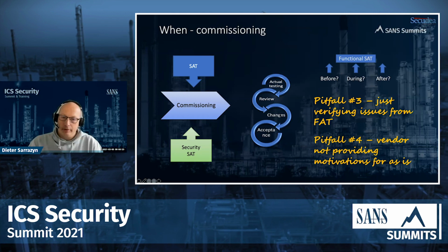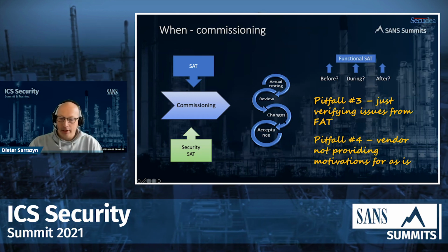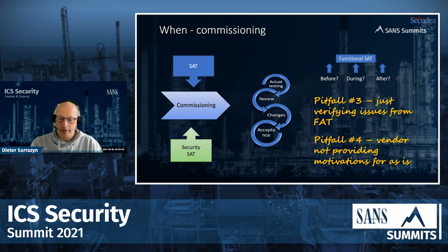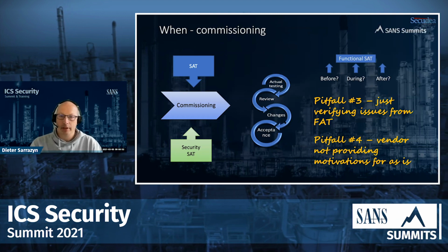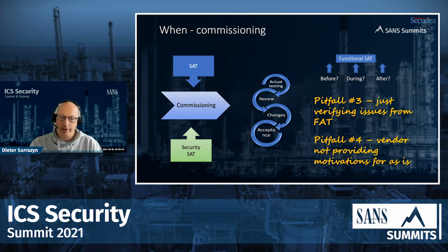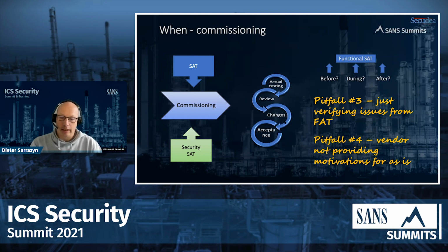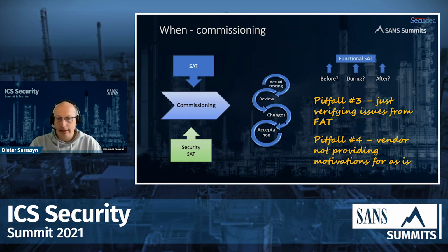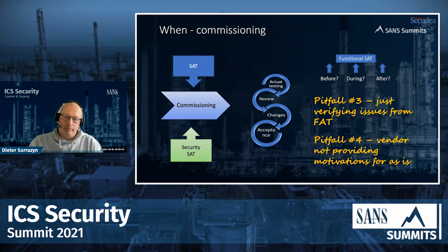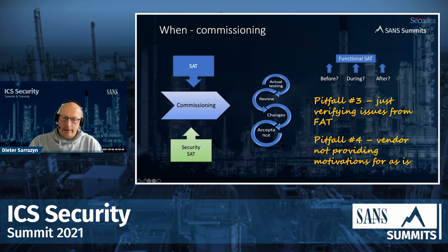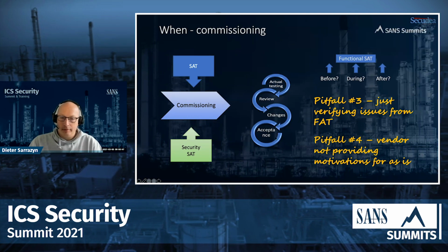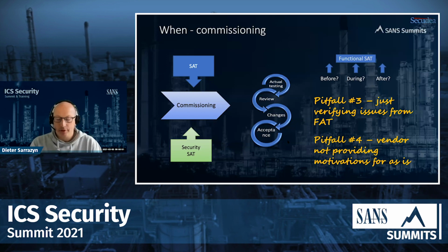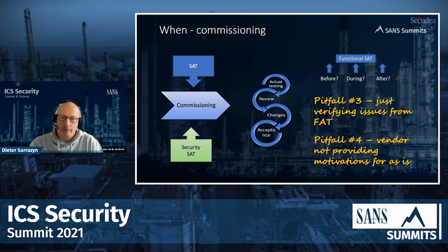Because as I mentioned during the FAT, sometimes you have proposed changes that cannot be done because of software legacy reasons, because of the software versions that the vendor is using, because of the type of PLC that is used, because of the type of environment that is used, and things like that. So at that time, you should go into the acceptance phase for that particular part, because you just have to know. We know there's a security issue, but you have to know it.